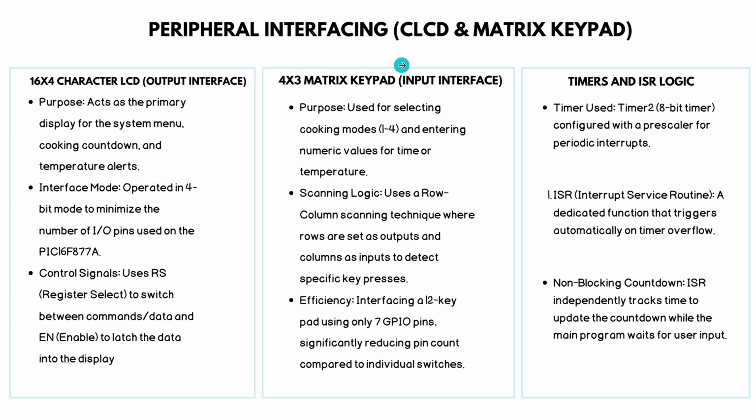Peripheral interfacing for CLCD, matrix keypad, and timers ISR. The 4 by 16 character LCD output interface. The LCD display is considered the output interface in our project. Its purpose is to act as the primary display for our start menu, cooking countdown, and temperature alerts. The interface mode operates in 4-bit mode to minimize the number of I/O pins used on